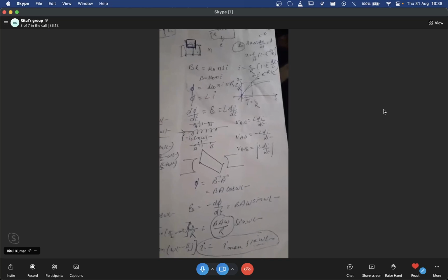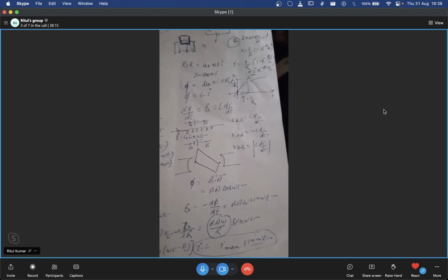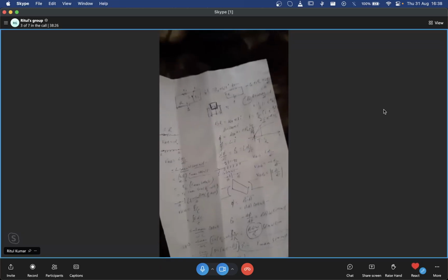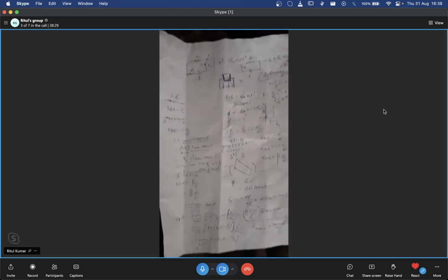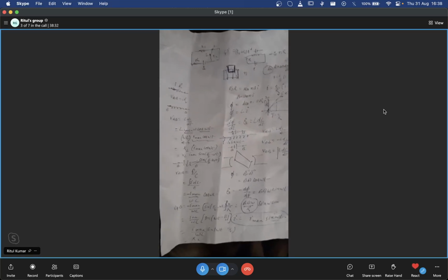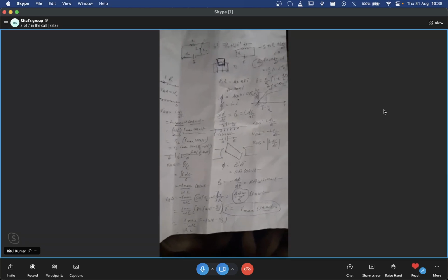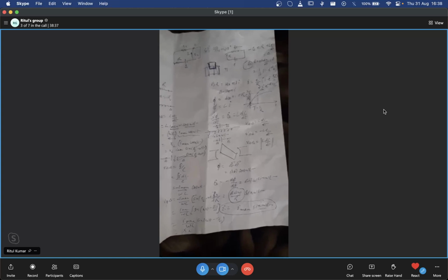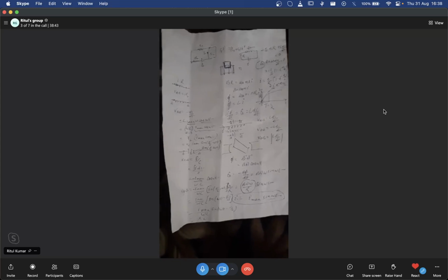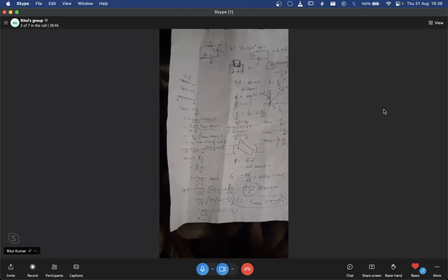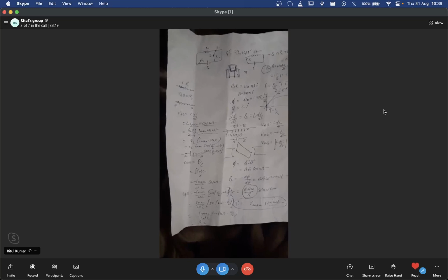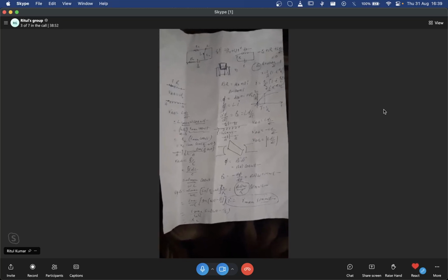Okay, you mean to say you are disconnecting it and leaving it? Then the current flowing through it will be zero. The moment current is zero, there will be no energy stored in it, so it can't just poof into nothingness, correct? Because energy will be stored in the field, right? Yes, sir. Energy is always stored in the field. The moment you devoid it of field, where will the energy be stored? So I thought it will still try to push current through the open circuit. Of course, it won't be able to, but it would maintain some sort of an EMF across it for some amount of time.